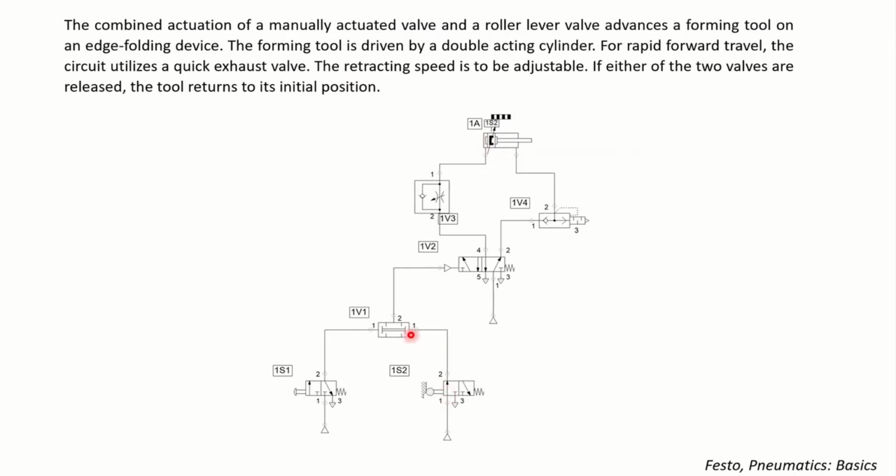This is sending a signal to the twin pressure valve. Whenever we push this button, the system starts operating, right? Now that combination, that condition, is met. Once the air passes through this twin pressure valve, because both conditions are true, it passes the air here. This pneumatic actuation will shift the directional control valve to its second position. Air will pass through this arrow, right, and it gets in here, and then we are at the throttle check valve. The throttle check valve has two paths.